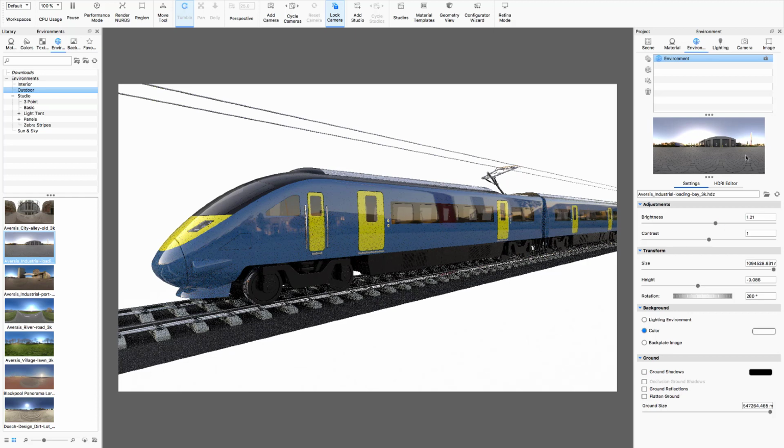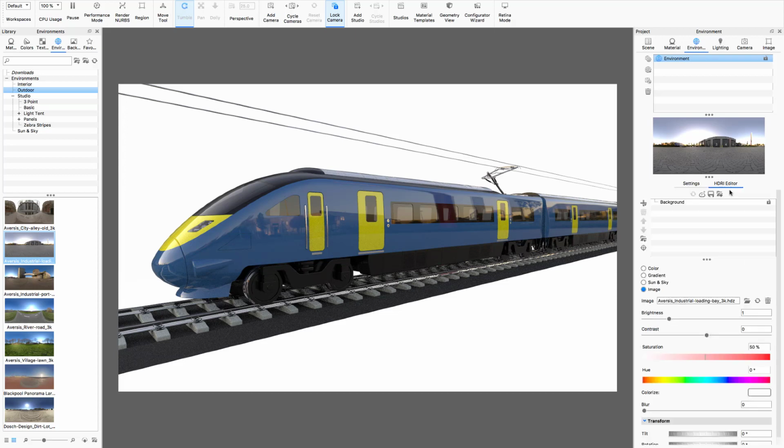And remember that if you use an image like this, this one perhaps is not too extreme in this respect, but sometimes we can heavily colorize our image by the color of the lighting environment. So in that case, we can go to the HDR editor and we can reduce the saturation of the image and make this image more grayscale. Okay, so you can see the preview up here. So this is heavily saturated, this is less heavily saturated. Okay, so make this much more neutral.